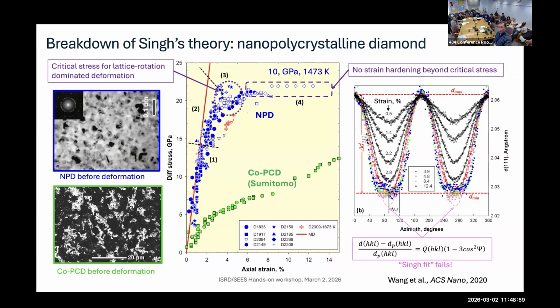Well, if you look at the diffraction pattern, you analyze the pattern, what's really interesting is beyond this point, the red dots, no matter how hard you deform the material, you will not exceed this part in the Q factor on the D spacing. So the material seems to have hit a really, really hard wall.